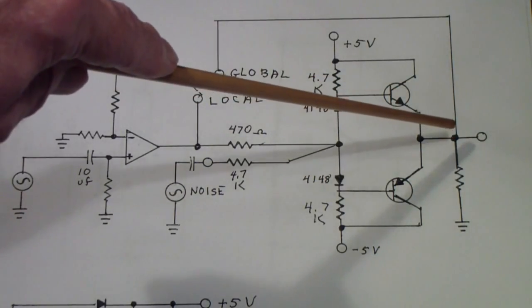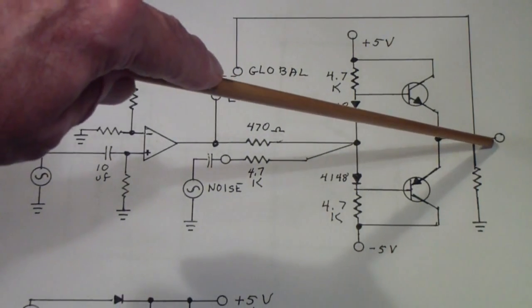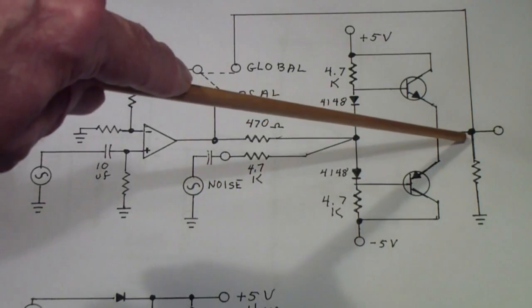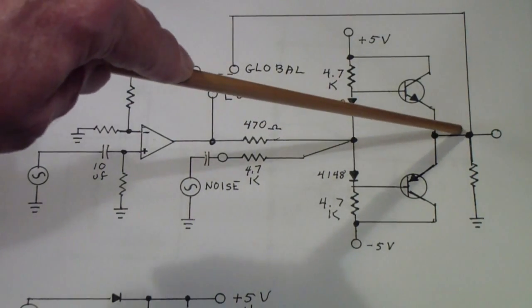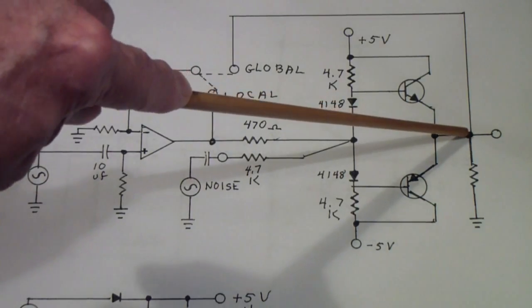The way you have to do that is you actually have to sense the current in this lead. And to do that, of course, you have to open the lead, insert something like a resistor in it, and measure the voltage across that resistor. And we'll talk about that in a minute. But this is node sampling.